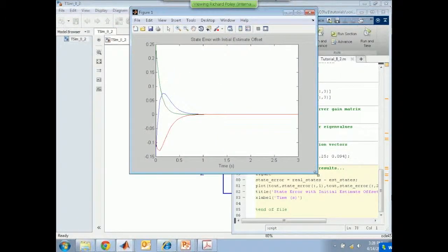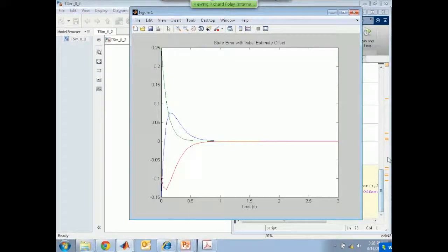And here we have, because we've selected these eigenvalues relatively far to the left, three states which for some initial condition error will converge on zero error after 1 second, which is what we're looking for. And the fact that the 1 second rule has been respected is because these eigenvalues are relatively far to the left, and I calculated what each of them will produce based on a first order approximation, because you know what the settling time is. It's four time constants. So within 2%, and that's what it gives me.